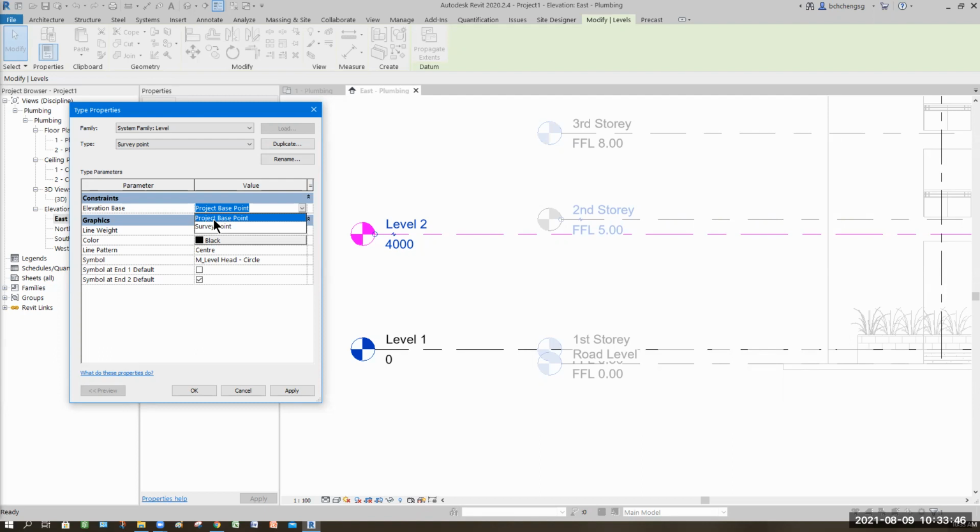Okay, project base point uses a move function. The move is basically this move. The one that I teach you for survey point is actually under Manage. It's called relocation or relocate. That's why, meantime, we want our project and survey to go at the same time, so I'm changing to survey point.